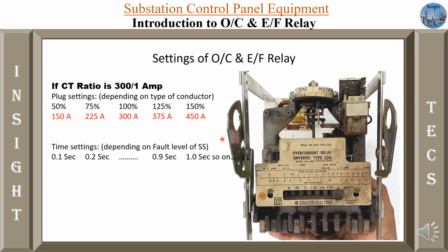So now we know that based on the IDMT curve the settings are done. As we saw in the video, there is a provision for plug setting multiplier selection over here, and this is a time setting multiplier. Okay, so now let's see how this plug setting is done.